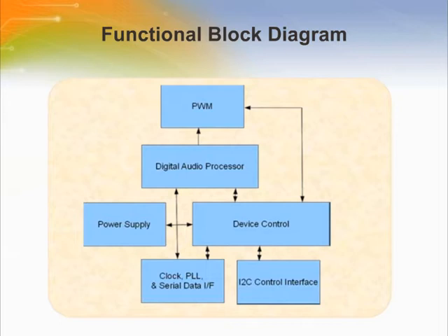The TAS5508C is a clocked slave-only device that requires the use of an external 13.5 MHz crystal. The TAS5508C operates as a slave-only, receive-only serial data interface in all modes. Its control section provides the control and sequencing for the TAS5508C.